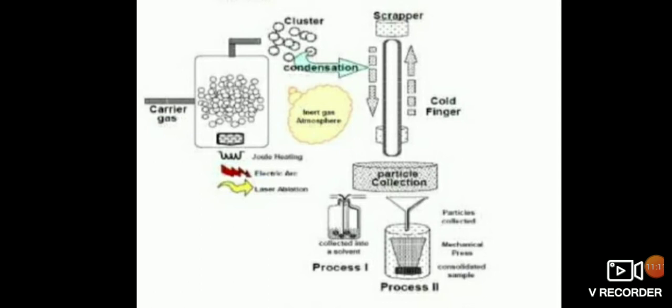It has been found that the particle size distributions in the gas flow systems, which are log-normal, are shifted towards smaller average size values with a reduction of the standard deviation of the distribution, depending on the flow rate of helium gas. Particle sizes are reduced by 80% and standard deviations by 18%.